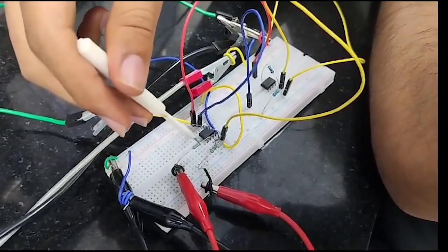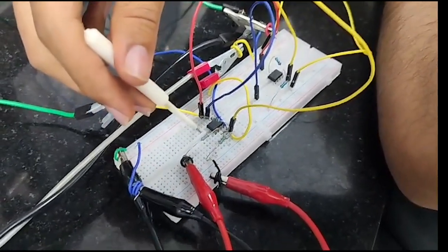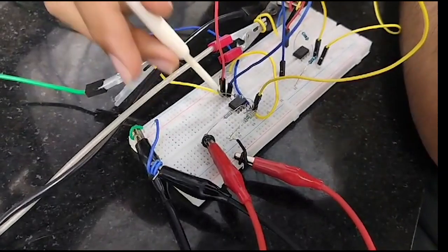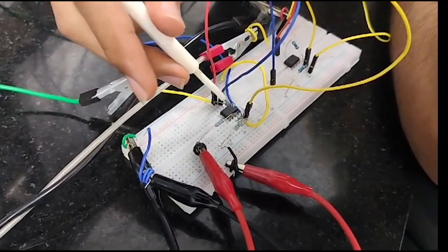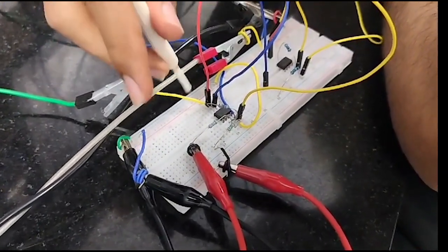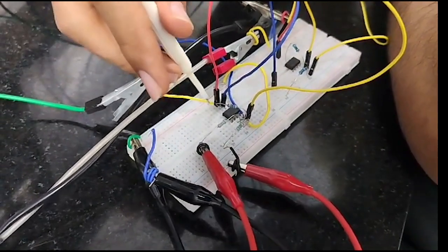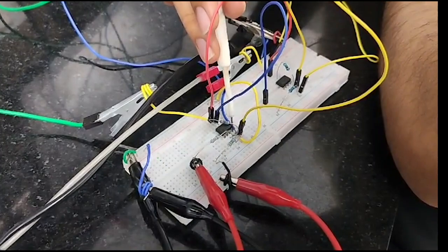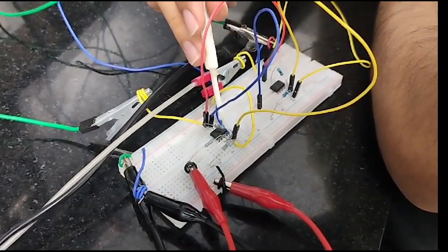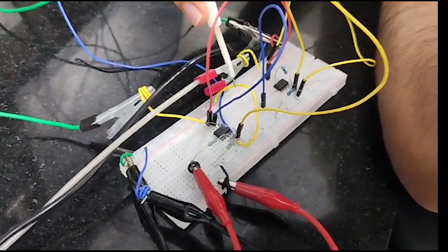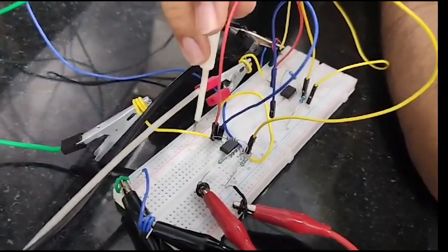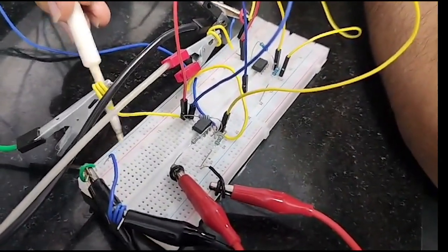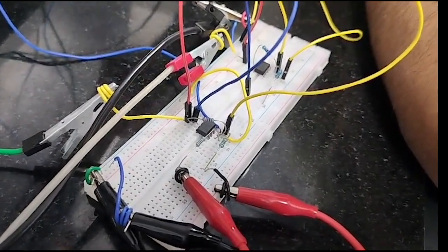These both are connected in parallel by 20 kilo ohm resistors, and then this IC has a feedback of 10 kilo ohm resistors, and this is our positive power supply, which is connected to the 7th pin, and this is our negative power supply, this blue wire, which is connected to the 4th pin, and ground. The 3rd, non-inverting pin is connected to the ground, and this is our common ground. You can see here all grounds are connected to this common wire.